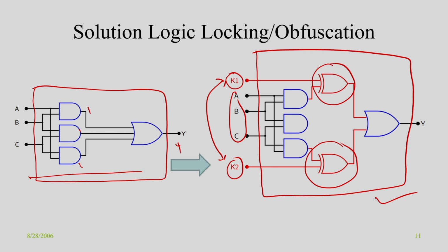So, this is the circuit. Now, what I am going to do, I just added 2 XOR gates here, and then I have just added a key. So now you see, if I give my key equal to 1 here, whatever the output is coming here will be toggled. That is the behavior of the XOR gate.